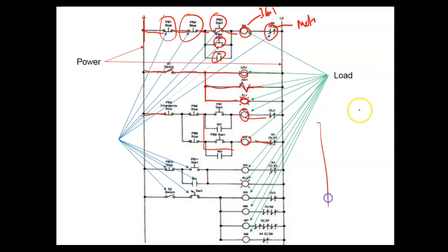We'll start off by putting our rungs, and then we'll come over here and put control devices, and then we'll come over here and generate an output. But this is going to be a simulated output, and then we're going to connect that to something on one of our output ports. But the language we're going to use is called ladder logic, or ladder.